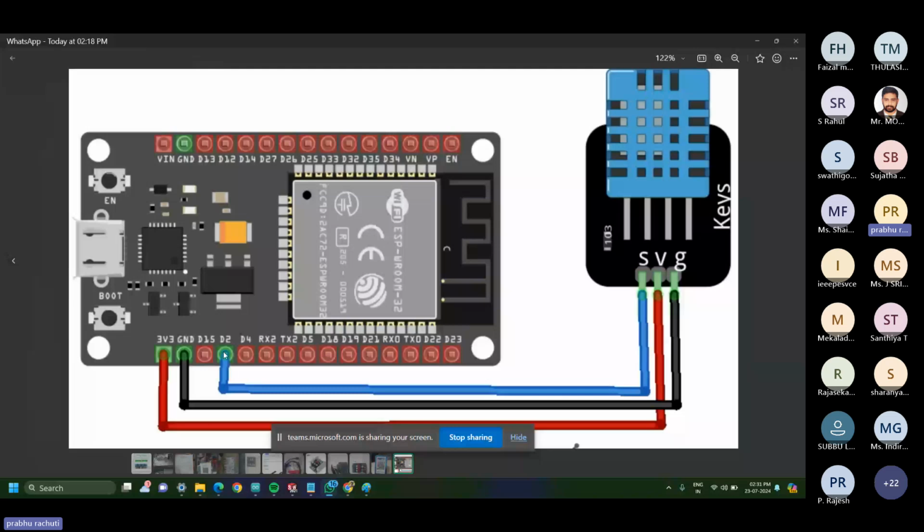Output is, for example, when you connect a relay module here. A relay is nothing but an electronic switch, if you are doing load control. In that case, the D2 pin serves as an output. To make that happen, you have to put it in output mode, and to do so, we have to use the pinMode command.